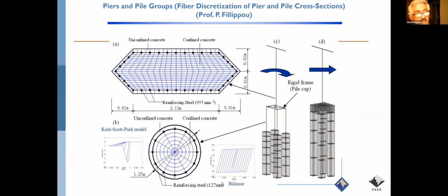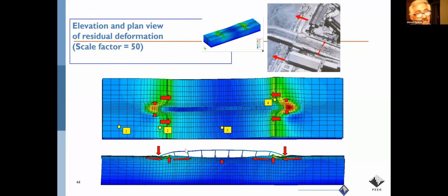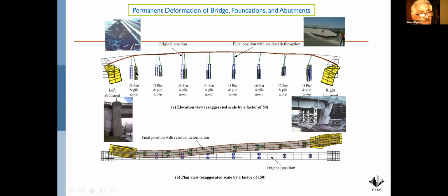Like I mentioned, we are building on fiber elements and advanced structural elements. So not only is the soil nonlinear, but also the ground is nonlinear. And as you see here in plan view, after the shaking, the approach ramps settle sideways, they spread out sideways. The land around the bridge moves down slope, and the ground in the middle here heaves because of the soil moving from both sides into the middle of the canyon. And then you see the deformed configuration of the bridge and the displaced configuration of the different piles.